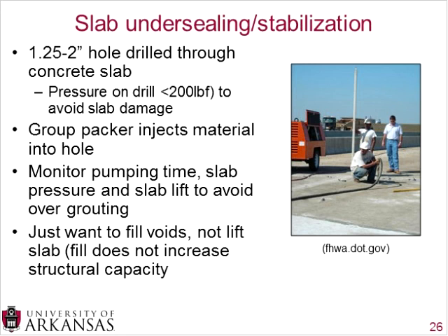And as you're injecting material, you want to make sure to monitor the pumping time and the slab pressure. You do not want the pressure to start building underneath that slab, because that can actually put forces on the bottom of the slab pushing up. And also you don't want any sort of slab lift. If you put too much grouting underneath there, you may actually start lifting the slab up, and then you're essentially creating faulting, which is another distress that you don't want to have.